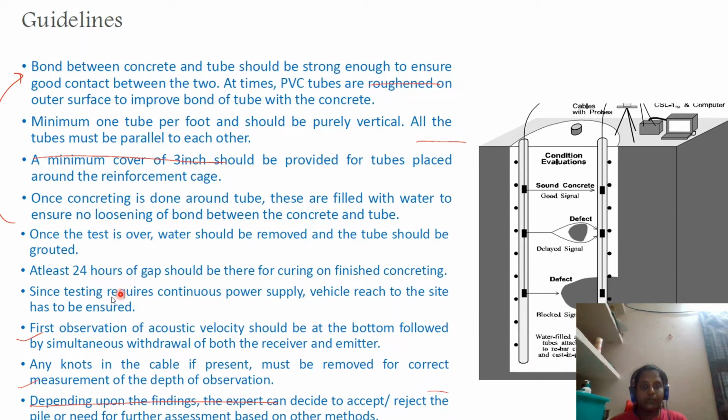So at least we have to give some 24 hours gap between your curing and finishing concrete. Since the test requires continuous power supply, we have to ensure that there is a continuous power supply. Any knots in this cable should be removed in order to have a proper reading. Depending on the findings, if you find any defect in our pipe, we can accept or reject, or we can perform a few more tests in order to confirm the result also.